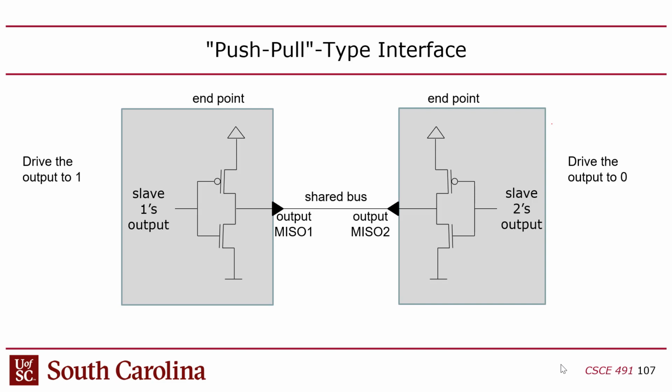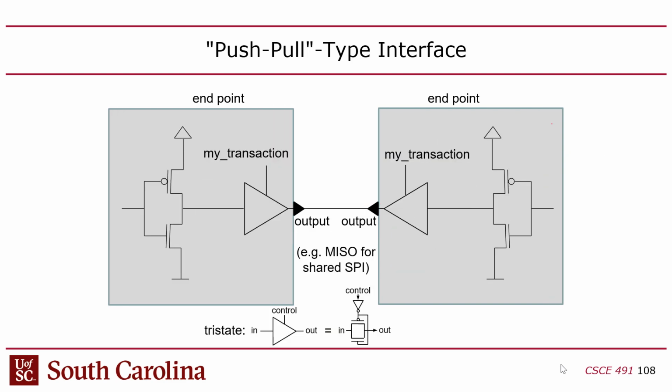Drivers are circuits on the chip that are emitting a 0 or 1 on an external wire. With a push-pull, you're actively shorting that wire to either power or ground. If you've got two chips and one shorts to power, one shorts to ground, you end up with a short circuit. A lot of current will come out of one chip and get sunk into the other chip.